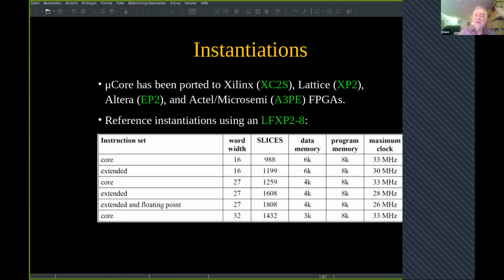Plus, if you look at the technology, it is next to impossible to build an A to D converter which is 24 bits. So a 20-bit architecture is what you usually need in order to solve your problems, and not 32-bit. And 27-bit is 24 plus 3 guard bits for rounding purposes.